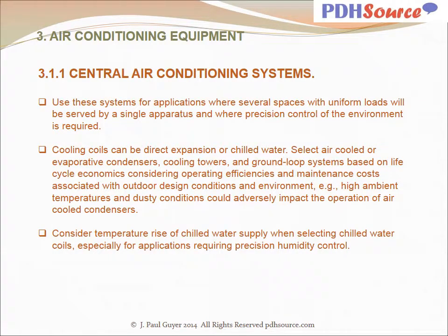So that's the fundamentals, if you will, of an HVAC system. You have the refrigeration cycle with the compressor, condenser coil, expansion valve, and evaporator coil, and that's what cools the air. And then for heating, you have a furnace or a heating coil of some sort.